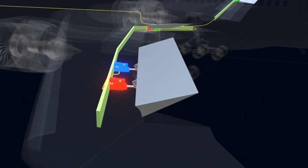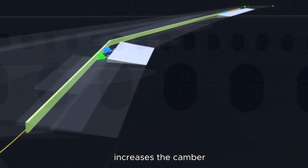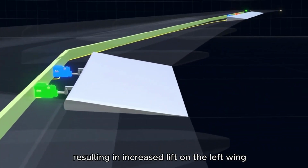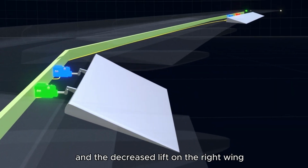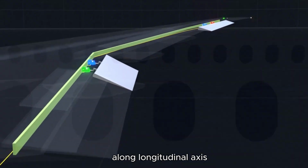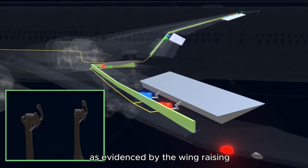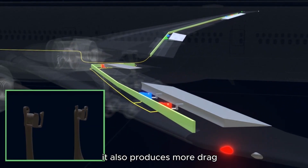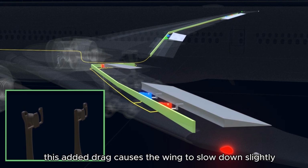right wing. The corresponding downward deflection of the left aileron increases the camber, resulting in increased lift on the left wing. Thus, the increased lift on the left wing and the decreased lift on the right wing causes the aircraft to roll to the right along the longitudinal axis. Since the downward deflected aileron produces more lift, as evidenced by the wing raising, it also produces more drag. This added drag causes the wing to slow down slightly.